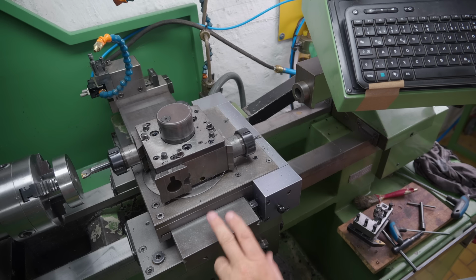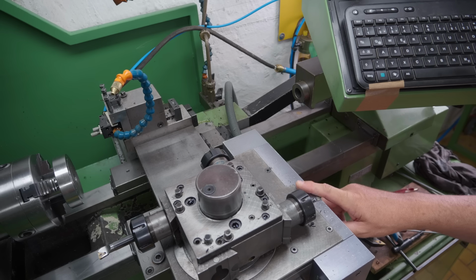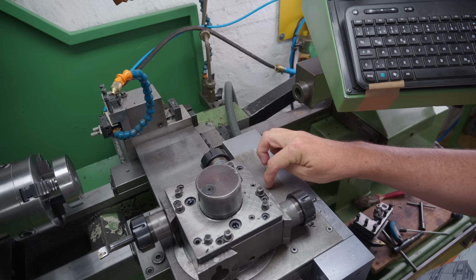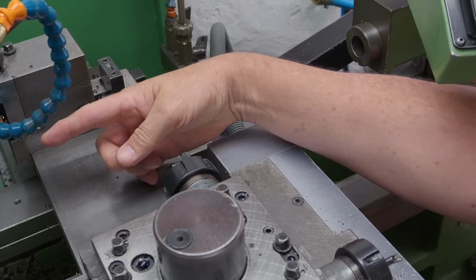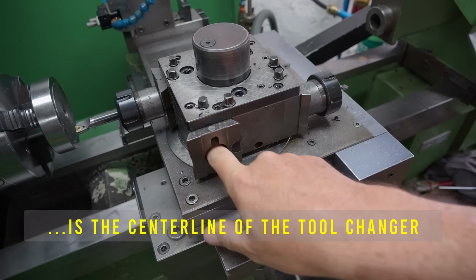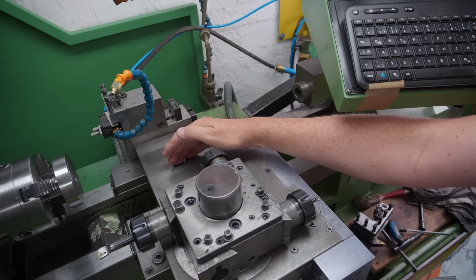Now, because the lathe's got a home switch on the x-axis, that position should be very accurate and repeatable, because after finding the home switch, I then use the next index count of the motor encoder to finalize that position. But I don't think I ever did the work to ensure that in machine coordinates, the 0 position is the center line. It's not essential, but since I'm in the process now of just checking things, let me see if I can work out where this ends up.